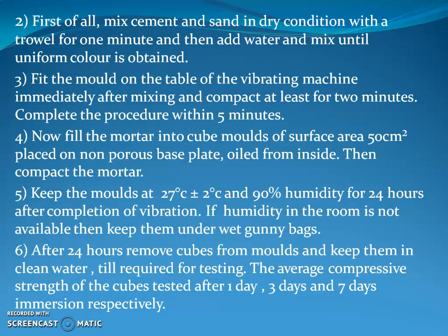Fit the mold on the table of the vibrating machine immediately after mixing and compact for at least 2 minutes. Complete the procedure within 5 minutes. Now fill the mortar into a cube mold of surface area 50 cm square placed on the non-porous base plate, oiled from inside. Then compact the mortar. Keep the molds at 27 degrees Celsius plus or minus 2 degrees Celsius and 90% humidity for 24 hours after completion of vibration.